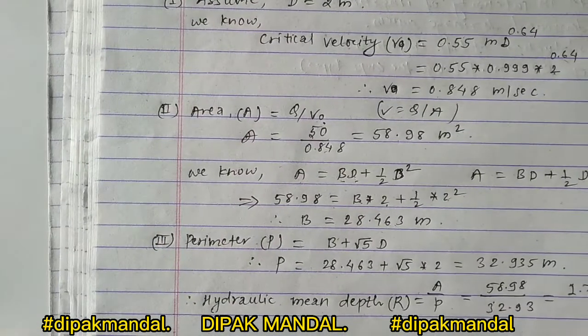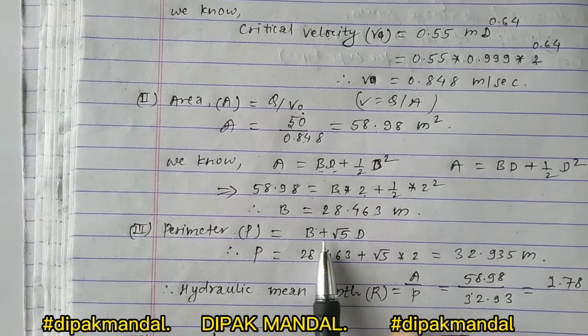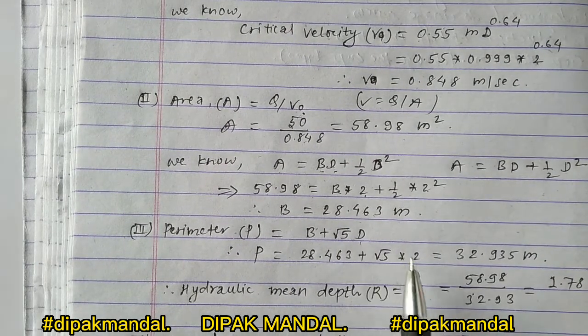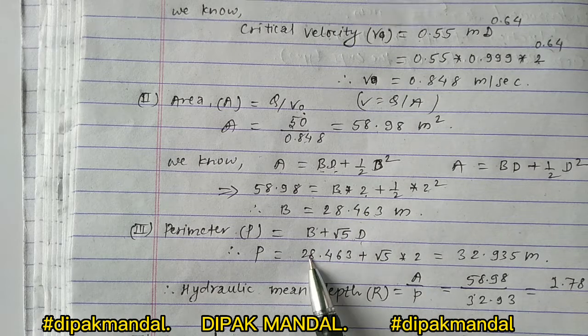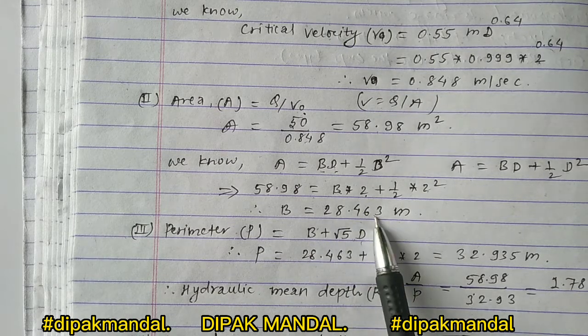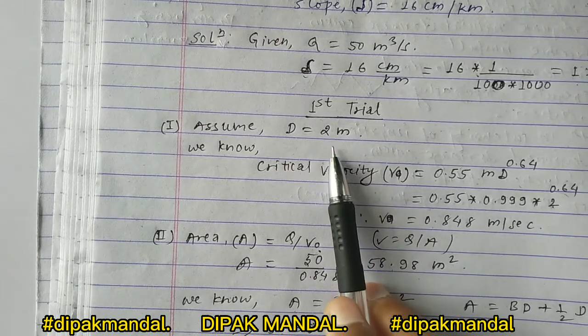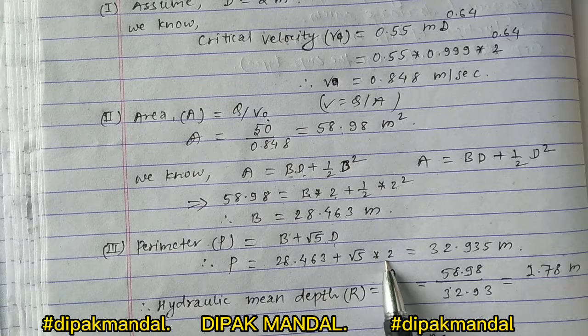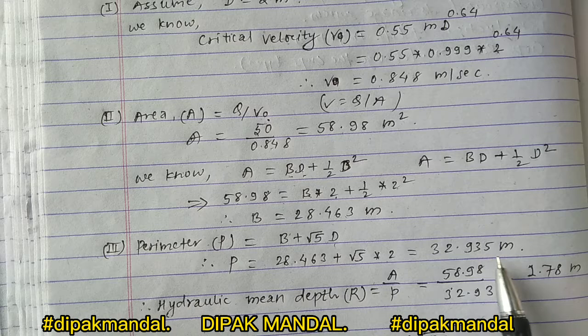Now in the third step we have to calculate the perimeter, and we know the perimeter P equals B plus 2D root under 5. Okay, and we use all these calculated values. The value of B we already calculated, 28.46, we keep here, plus root under 5 times the value of D, which is the assumed value, and we take 2 meter. Okay, and we just keep 2 meter. After calculating this value we get the perimeter, that is, the value of P equals 32.935.